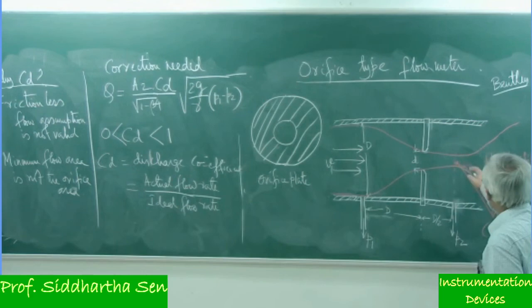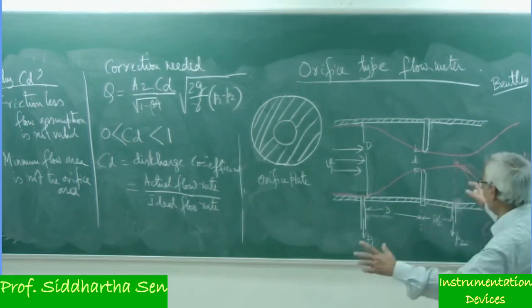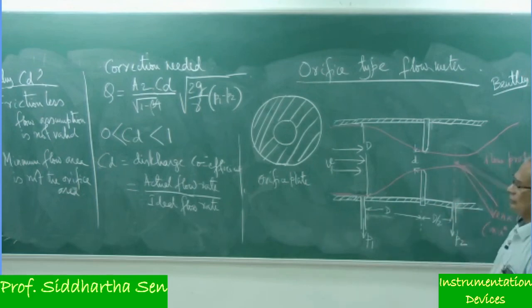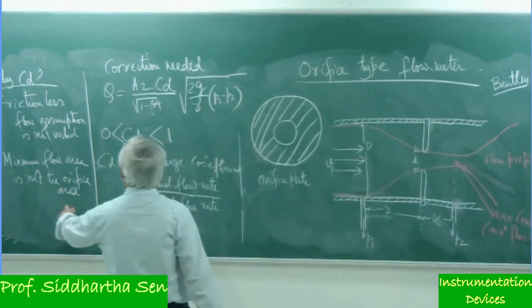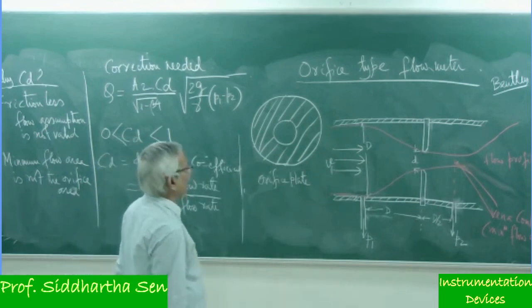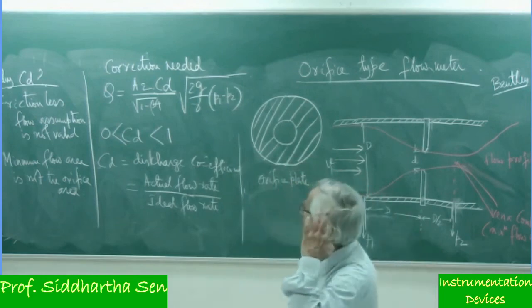And we put our tapping not at the orifice, that's why, to get a larger A at the point P2, where the vena contracta is occurring there. So naturally, this flow area is further reduced, and the frictionless flow is there, and that is an important thing that will give you inaccuracy.